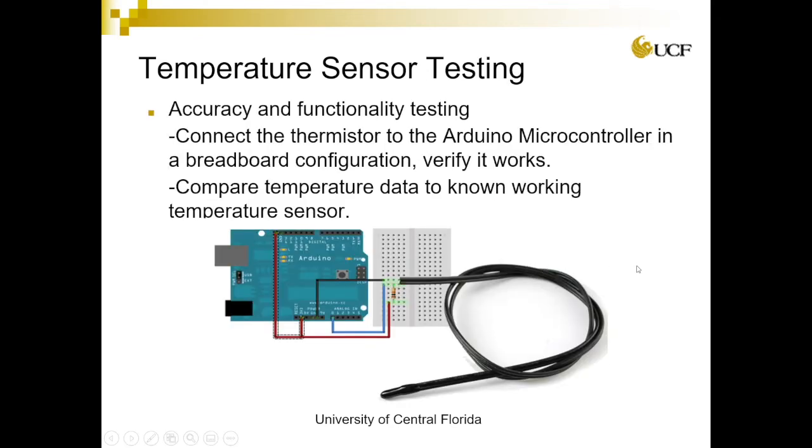To test this sensor, we intend on connecting it to a breadboard with a pull-up resistor and using an Arduino. We are going to just run some code through it, make sure it gets some temperature readings, and compare it to a known good temperature sensor.